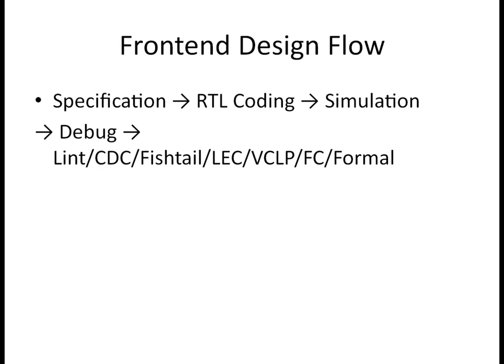Next is the multi-driven net issue. In a multi-driven net issue, multiple drivers, meaning different inputs, are assigned to the same output. In that case the tool will tell you there is a multi-driver issue. We need to make sure which input should drive that output, and fix it in the design.